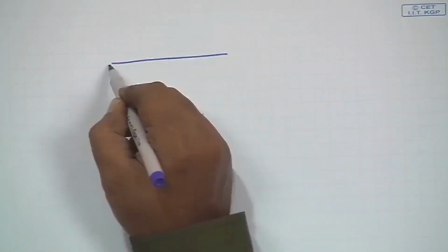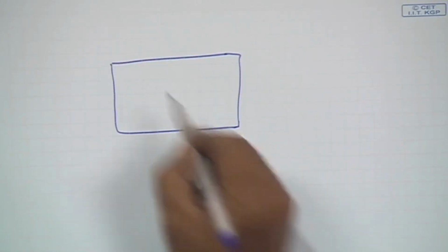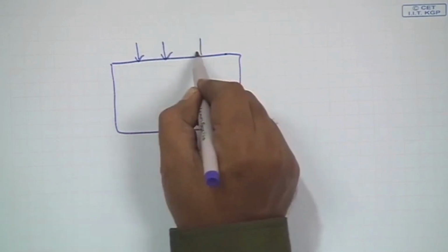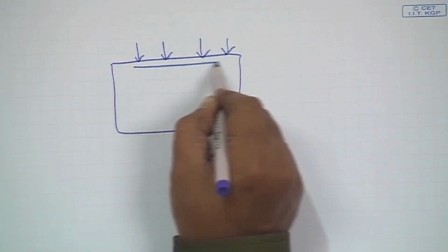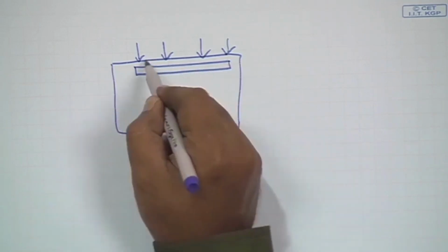That is why the storage elements of the control path may be replaced by scan cells, whereas storage elements on the data path are not put on scan cells, because ultimately the values will be coming from the system primary inputs. In fact, any digital design, if you look into it, is like this. If this is the system boundary, we have the inputs coming from the outside world, and at the first stage there will be registers holding these values.